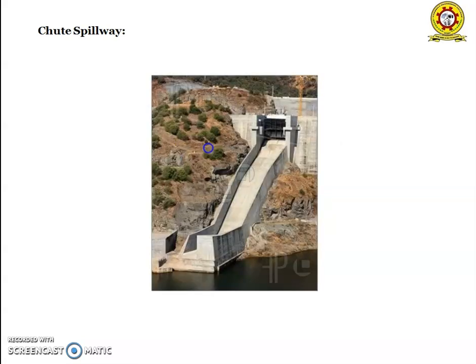And the second one is the chute spillway. Chute spillways are common and basic in design and transfer water from behind the dam down a smooth decline into the river below. The spillway slope and its sides are lined with concrete. In the case of sufficiently stiff foundation conditions at the spillway's location, a chute spillway may be used instead of an overflow spillway due to economical considerations.